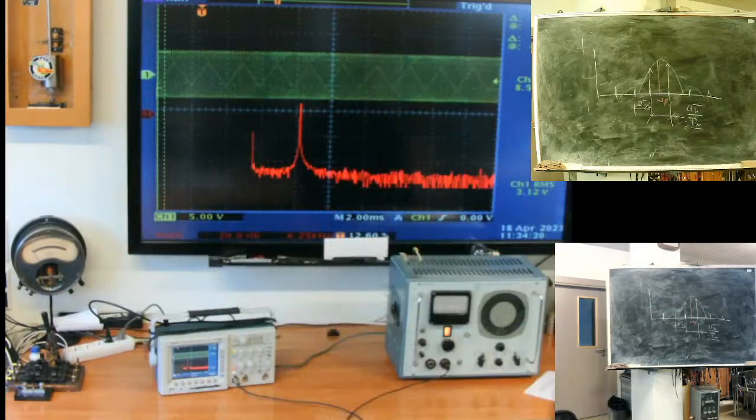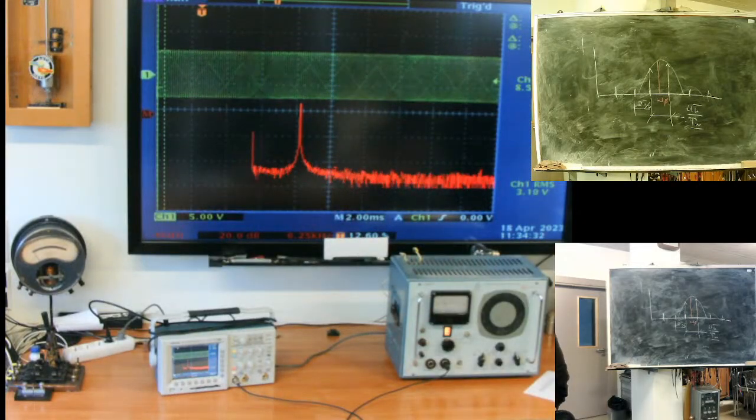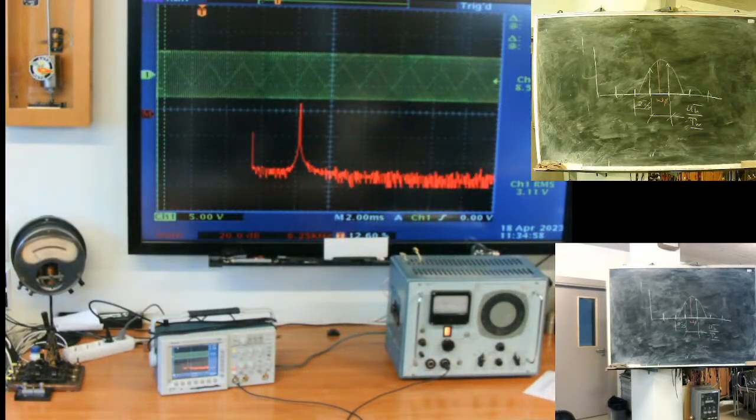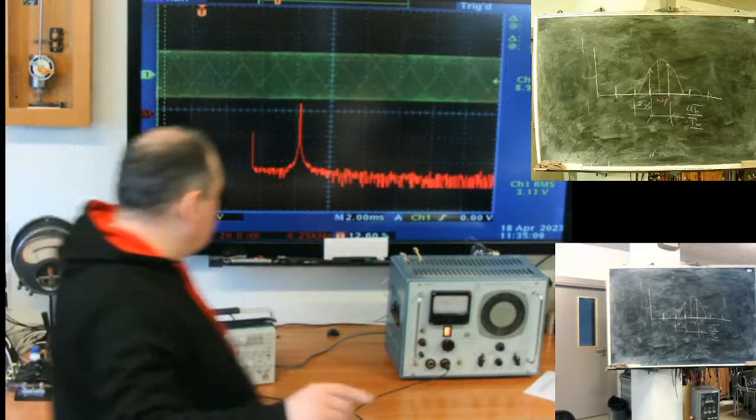But what does elongation of the observation window mean? The system becomes slower. And if you want to record a transient, you want to record a sound, what will you get? This transformation is the base of all MPEG conversions. You will get some kind of average. So elongation of the window is good for a stationary signal. But when we need to deal with a transient, it will not only slow down, it will smoothen transients. We will get a result of something average.